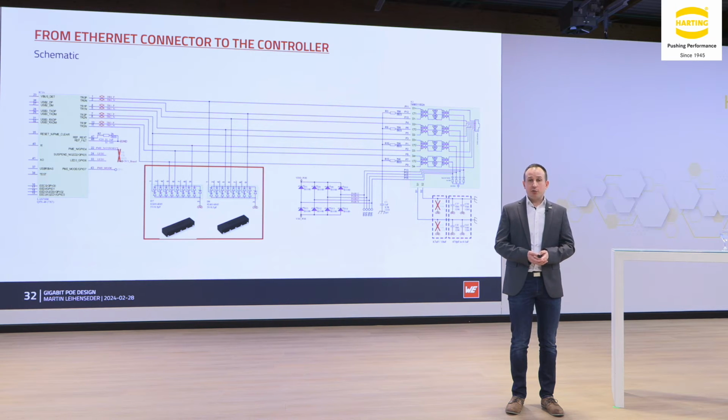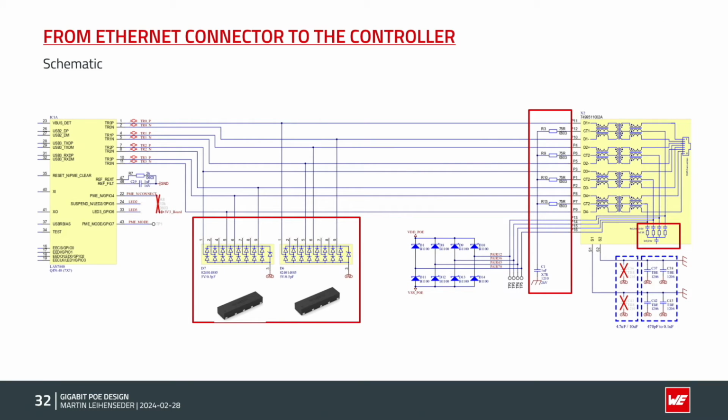Those elements are very small. And then we have here on the LAN transformer a ground termination called Bob Smith termination. This is the small area here and the bigger area. This is also ground termination that we did. This ground termination is a bit special. We did this for EMI reasons, because we put our board, of course, the actual one, in EMI testing, and so we also made a ground termination on the secondary side with 75 ohm resistors for the signals coming from the controller side.